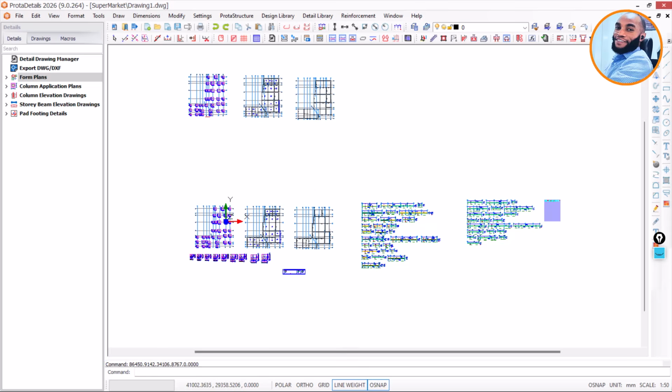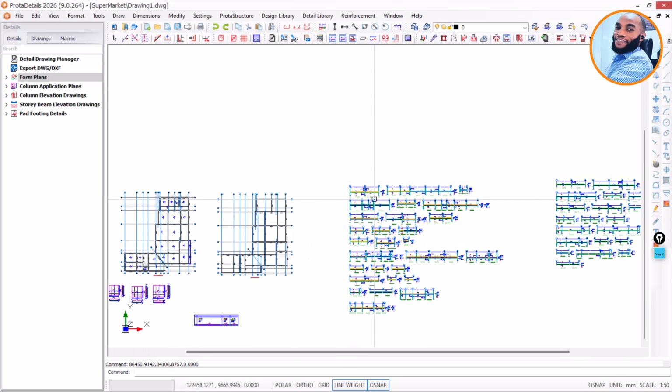The next thing now to achieve is the beams. So I will skip this column layout for now, and move to the beams. Then for the beams, I'll click on this arrow down here and then click on the first one. Now it is for the beam that you need to do some settings before you can paste your drawing. It's a must, you must do that.